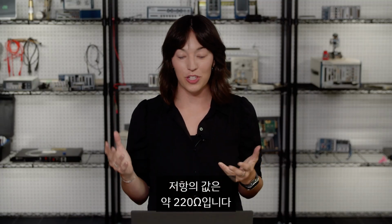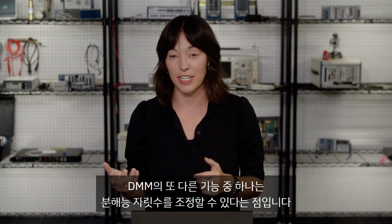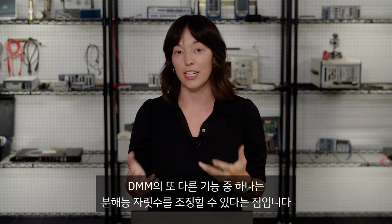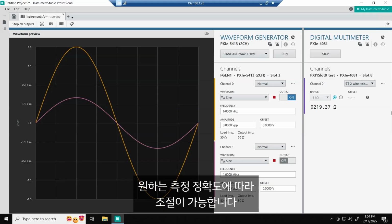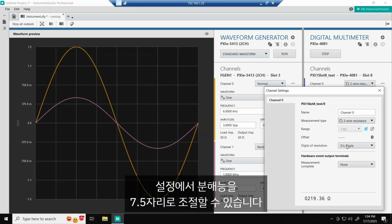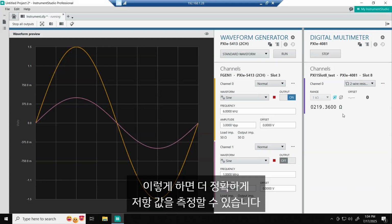Okay, so we've got about 220 ohms here on our resistor. One of the other things about our DMMs is you can actually change the digits of resolution depending on what you're looking to get out of your DMM. If I go up to this, I can change my digits of resolution to say 7.5 digits, and that will give me a more accurate reading here on my resistor.